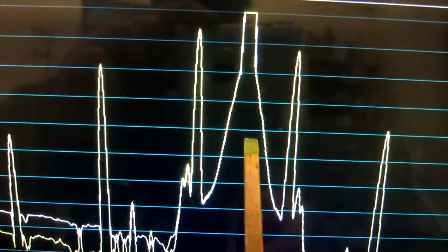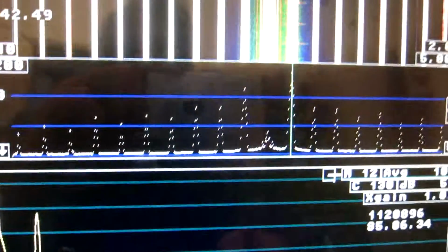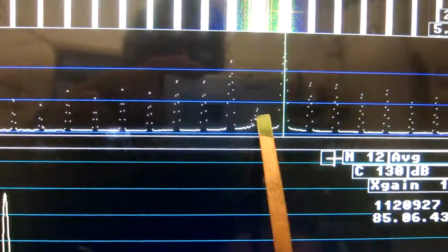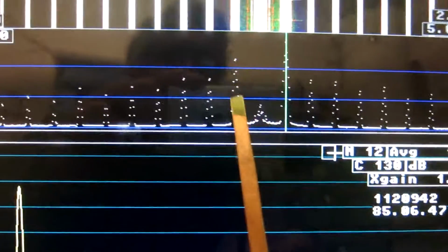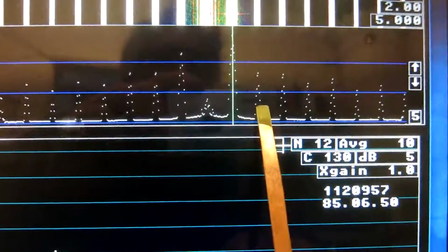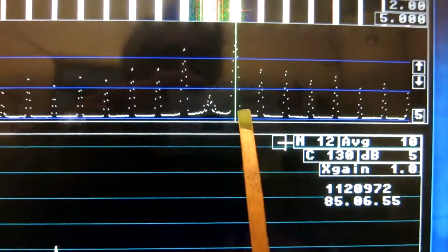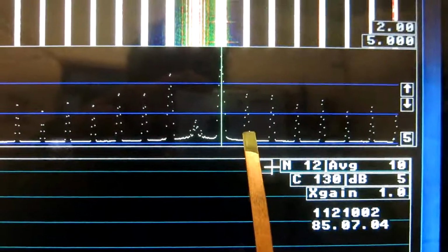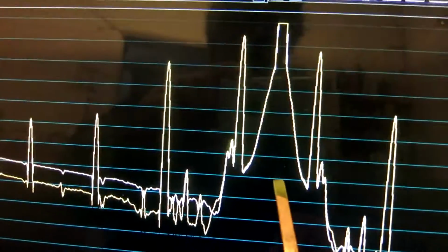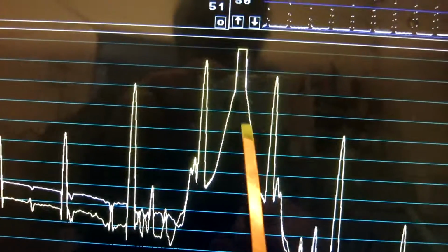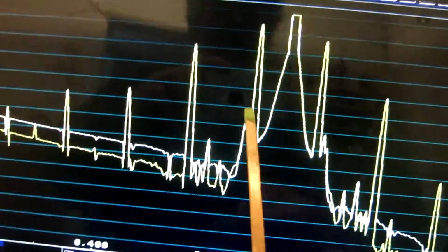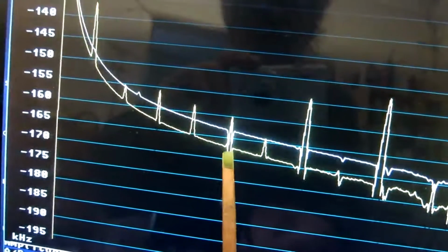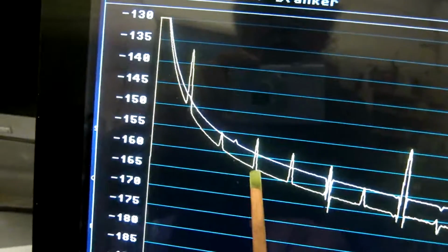That is the DC, because I'm using two direct conversion receivers, and here is the center, which is 0, and here is the carrier at 700 Hz, and here is the mirror image, and here is 1400 Hz. It's the double this frequency. Probably from the mixers, because there are 20 megahertz overtones generated internally in the mixers. Anyway, they give this peak at 700, which is totally uninteresting, and it is surrounded by 50 Hz, 100 Hz, 150, mainly odd overtones, 250, 350, 450, and then it coincides with the 50 Hz overtones.